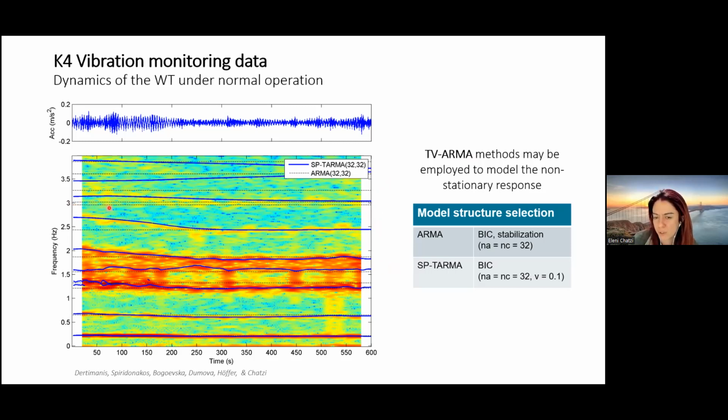Now, the standard approaches would have given you predictions that are usually averaged, something that looks like the dashed lines of this example, and which is really a very rough approximation that oftentimes, at least for our tasks, is not sufficient for predictive purposes. In fact, we need to have this kind of flexibility that tracks the variability within the windows of interest. Now, the problem in what I present here is that such a model I can fit within a 10-minute horizon, which is the typical amount of windows within which we gather also our SCADA information on the mean wind speed and direction.